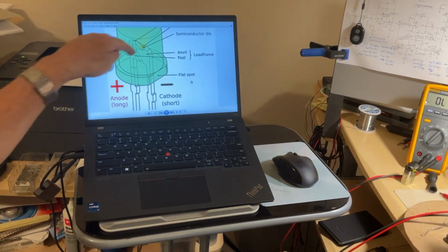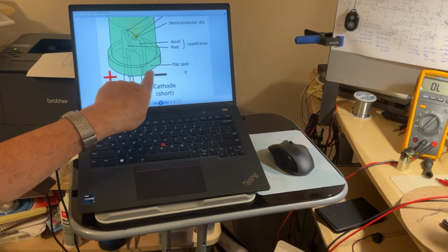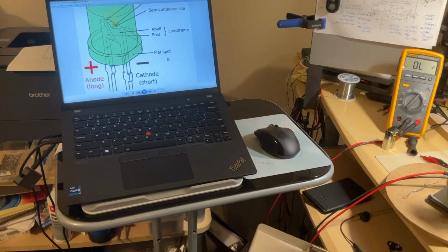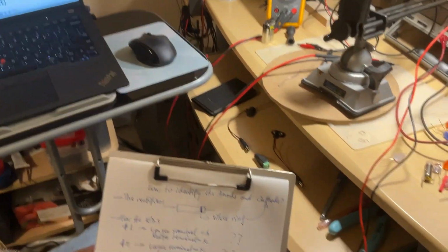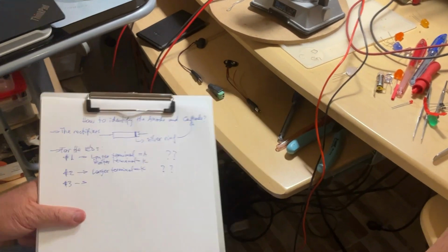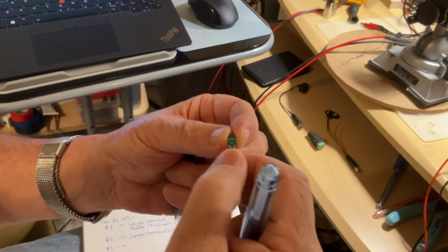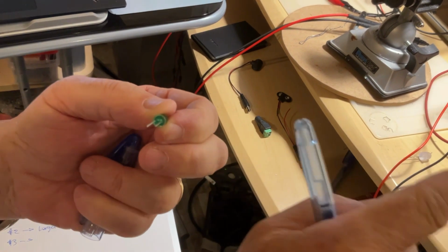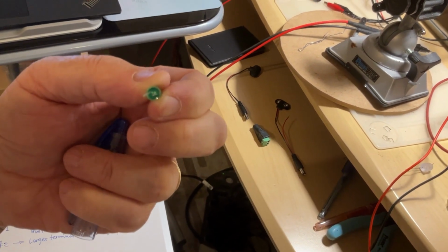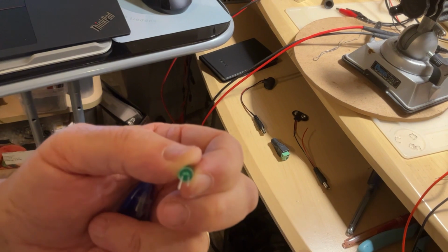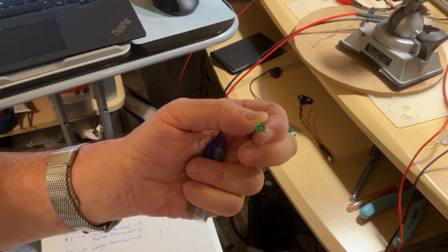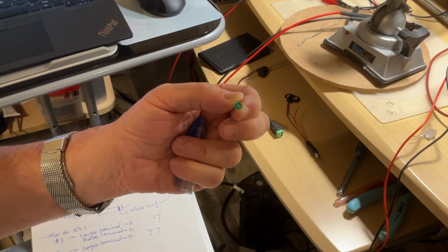They say here, hey, on the circular end of the body for the diode, there is a flat spot. And that flat spot is identifying the cathode. So I'm gonna find such a diode for you right now. You won't be able to see it properly from a distance. But here, on the right side, there is a little flat spot on the diode body. And yes, this one is representing the cathode.